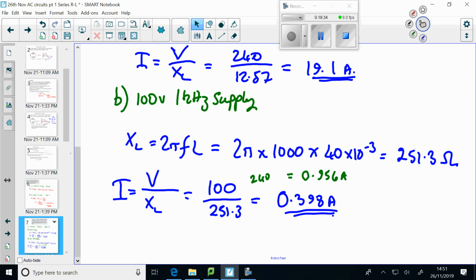We had a problem where someone replaced a DC coil relay with an AC one, worked for a small while, faulty again. Take that one out, 24 volts AC, put another 24 volt AC coil in, and so it went on until somebody actually got the drawings out and checked and said, hang on, this should be a DC relay, and then the problem was solved. So there are significant differences in that practical situation between the DC resistance of two coils and how they work in circuits. Right? Are you all okay with that so far?